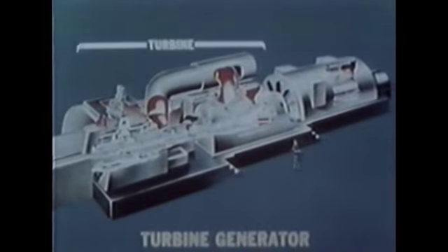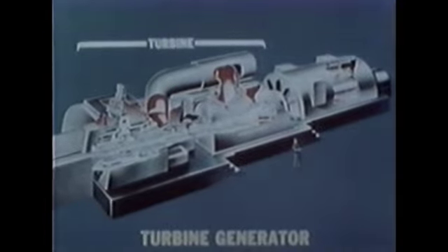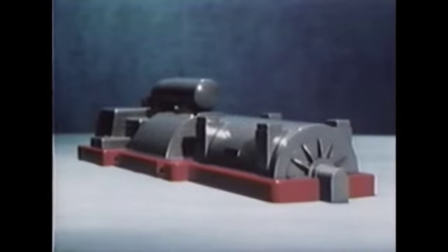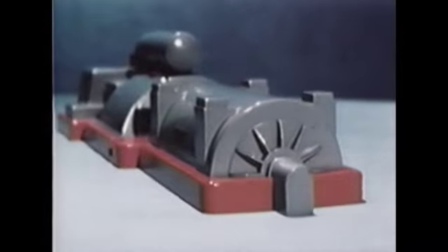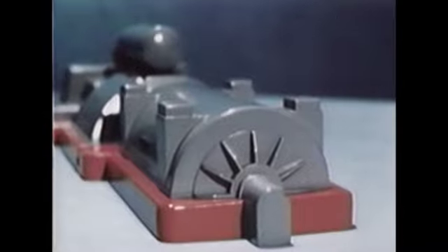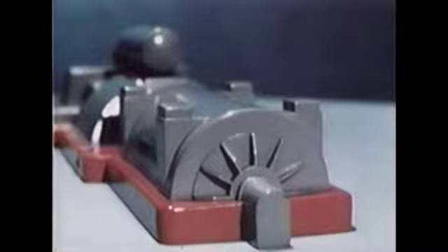This is supplied by a DC generator called an exciter, which is often located at the end of the AC generator. The turbine uses the mechanical energy of steam to drive the generator. As the electric power demand increases, the turbine's governor allows more steam into the turbine to keep the generator running at a constant speed, or frequency. At the same time, the exciter will cause the generator's DC field current to increase in order to maintain a constant magnitude of the generated AC voltage.